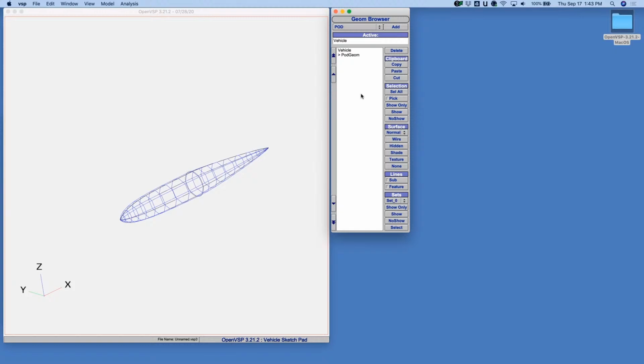Yeah. So Russ just asked about the lift equivalent area in the wave drag. Right now, I'd say there's no plan for that. You should be able to run VSP Aero in supersonic mode to get the nose to tail lift distribution, and from that compute the lift contribution to wave drag, and also the lift contribution to the sonic boom.